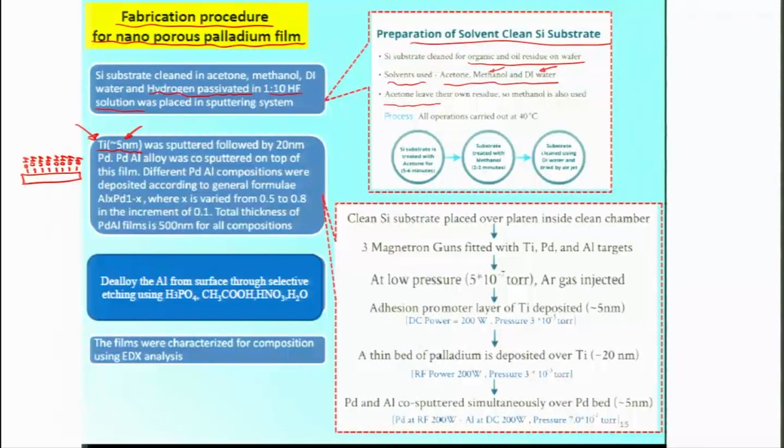Sputter coating is a sort of vaporization process where there is a metal target and a plasma is generated. The plasma knocks off some of the metal and carries it towards the bias that the plasma system has, and typically the substrates are on the ground plate, where this bias voltage drives the plasma along with the material to the surface.